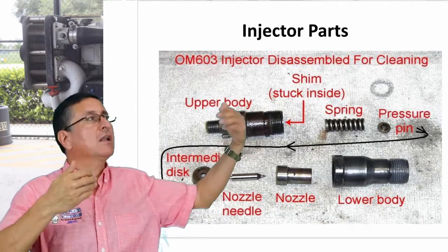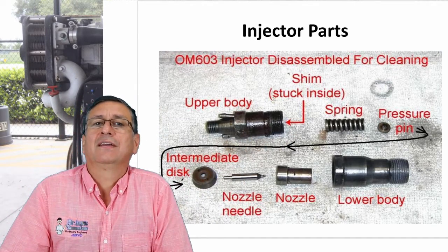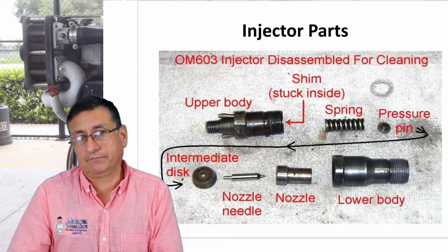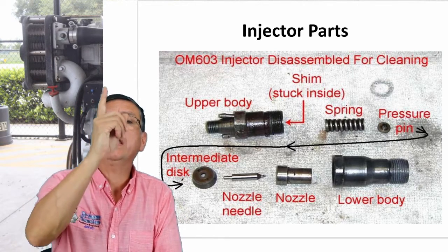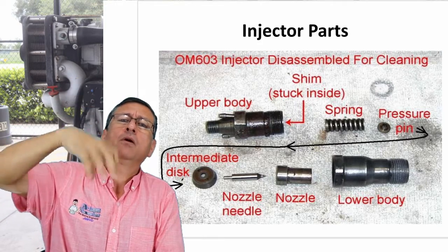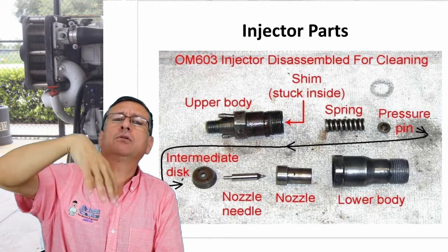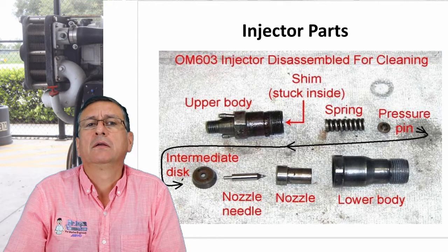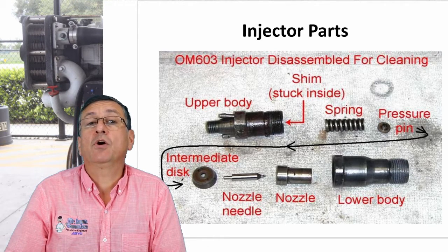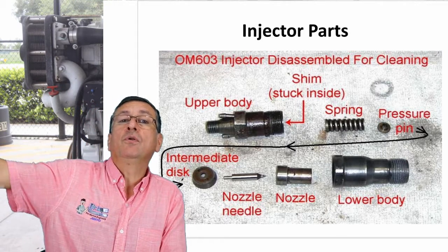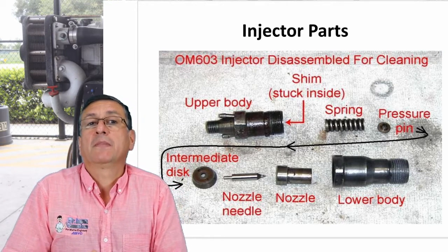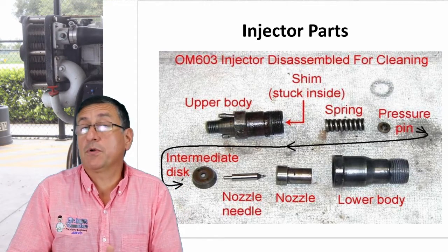And what is the external symptom? You have black smoke. Of course, because one injector is leaking fuel constantly into the combustion chamber. You have black smoke and probably you have a lot of fuel outside through the exhaust pipe. This is in case that the injector is broken.